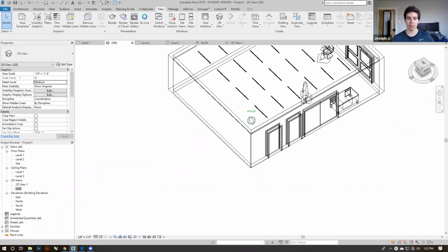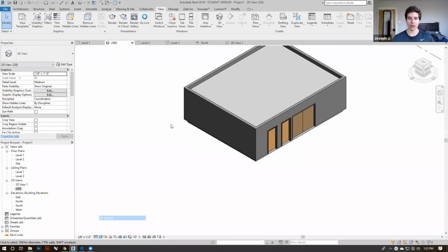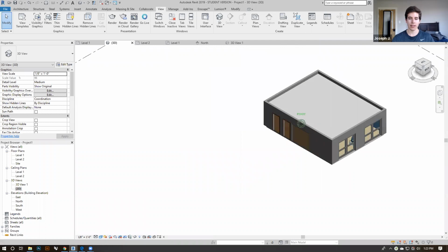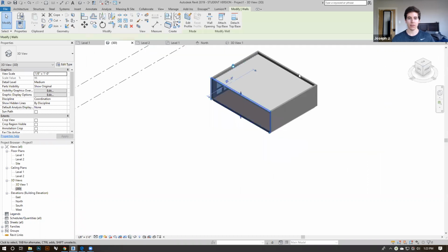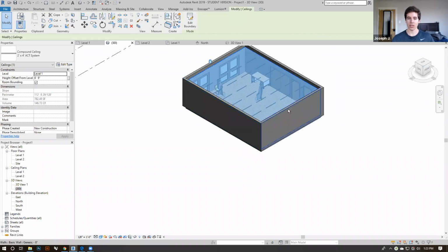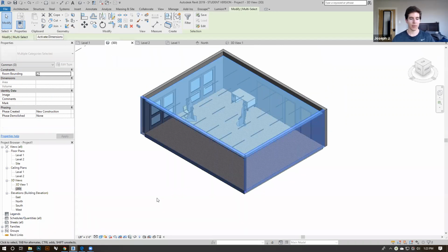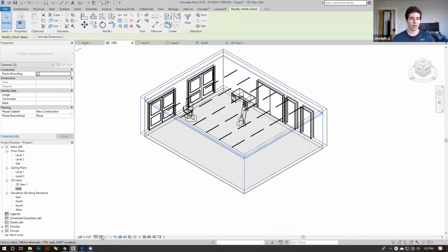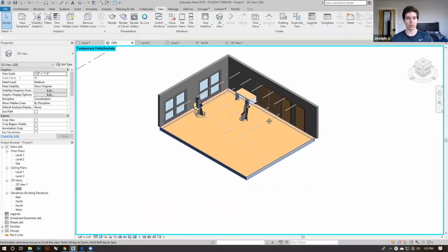But I'm going to add, don't stop the class, but if you're good with the model, you can actually do different angles. So one I like is the exploded axonometric. This is more of something you'd see in engineering drawings. If you worked with Legos as a kid, this is how Lego models were presented and how most CAD drawings show their models. So this is isometric. And I'm going to select just the parts that are in the way of my model. And I can go to my little sunglasses icon that's very small down here. I can go to hide element,